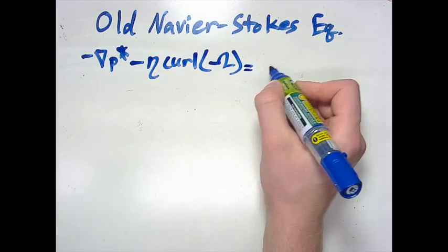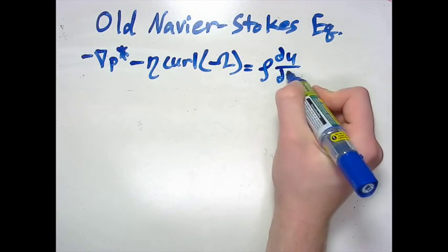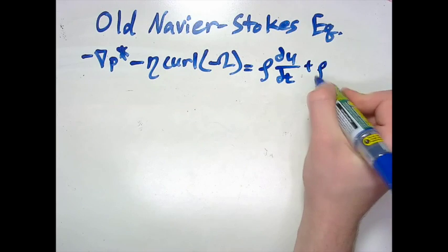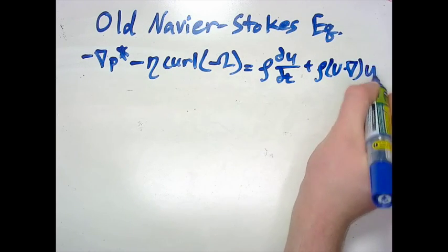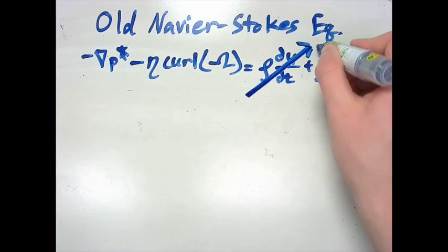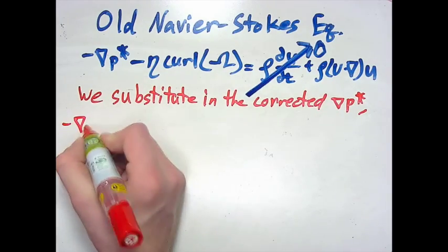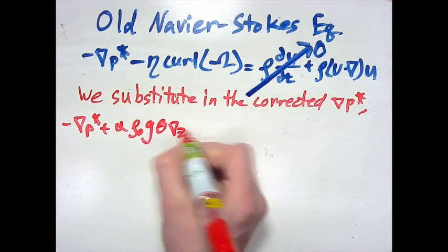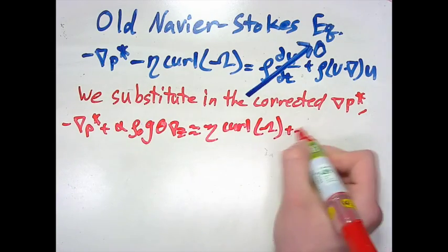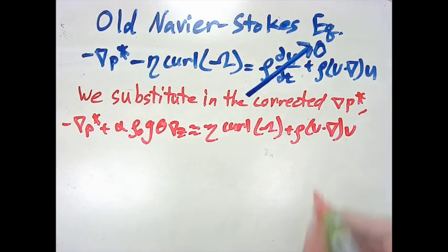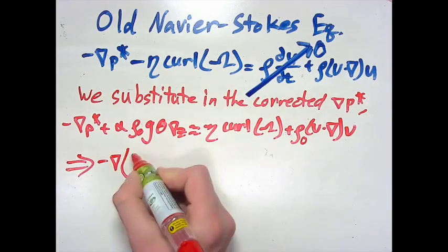Here we have a regular Navier-Stokes equation. We will assume that convective flow is normally steady flow, where du/dt is 0. Substitution and simple algebra give us our corrected Navier-Stokes equation that includes thermal effects, and is the first of the Boussinesq equations.